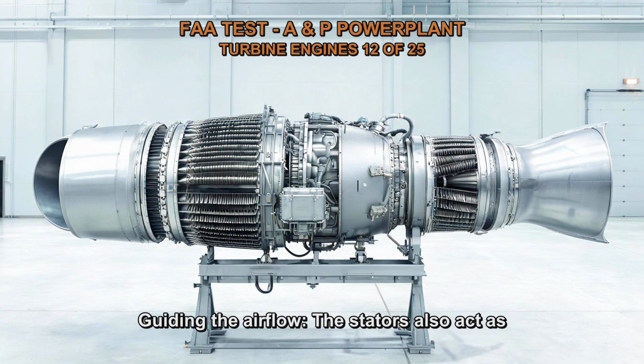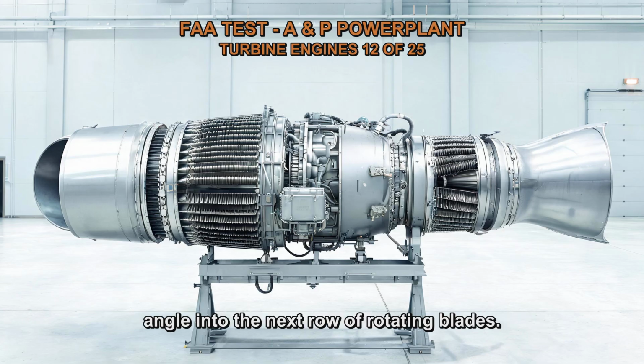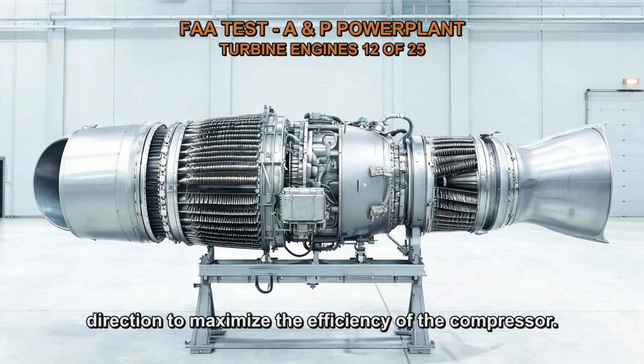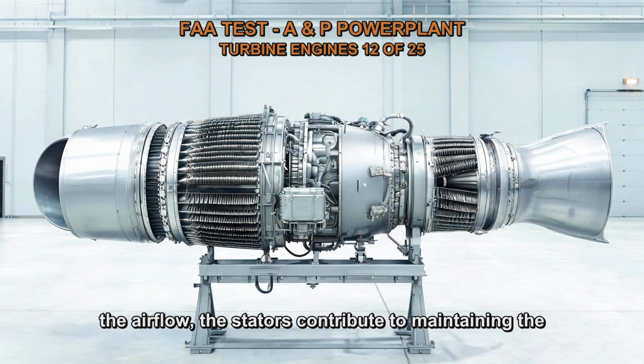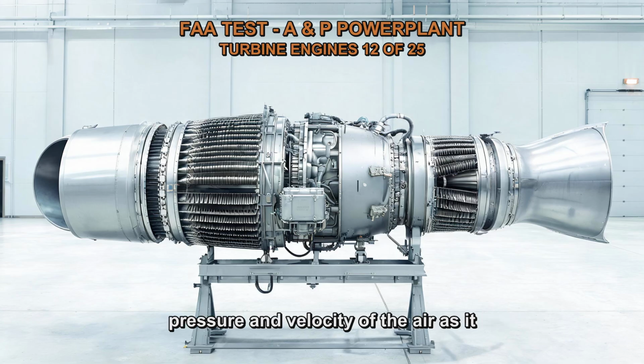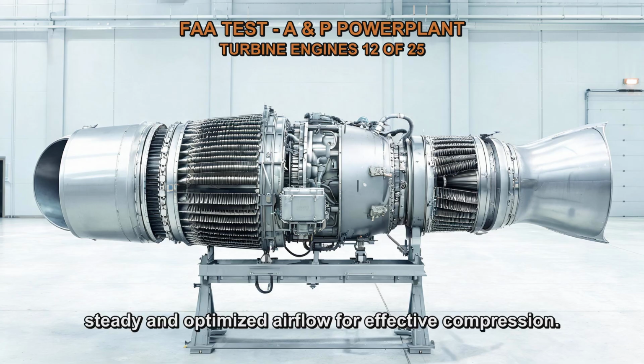Guiding the airflow, the stators also act as guide vanes, directing the airflow at the appropriate angle into the next row of rotating blades. They help to control and manage the airflow direction to maximize the efficiency of the compressor. Maintaining pressure and velocity. By diffusing and guiding the airflow, the stators contribute to maintaining the pressure and velocity of the air as it passes through the compressor. This ensures that the rotating blades receive a steady and optimized airflow for effective compression.